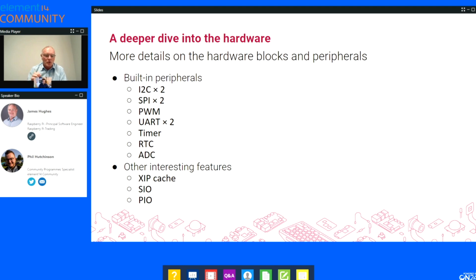The guy who designed it, I had to get him to explain how it all worked. And it's really quite a sophisticated system. You think PWM is just pinging a line up and down, but actually these ones are quite clever and well worth looking into. So with 8x2, we've got 16 controllable PWM outputs, which can be spread all over whichever GPIO you want.